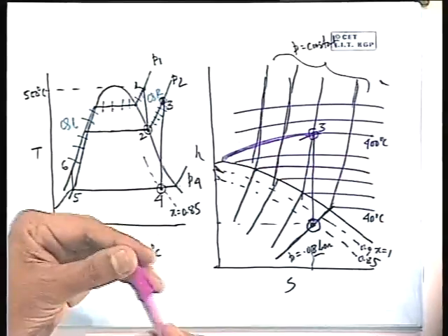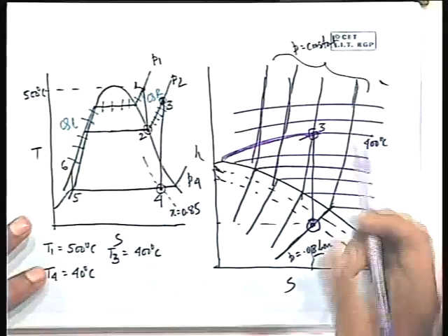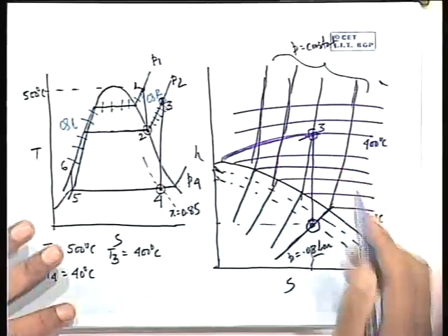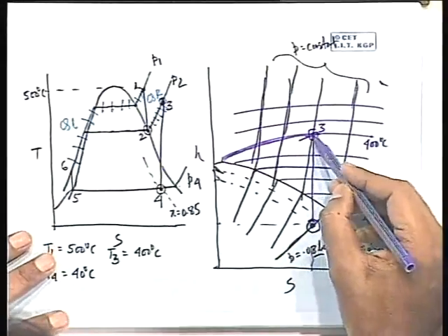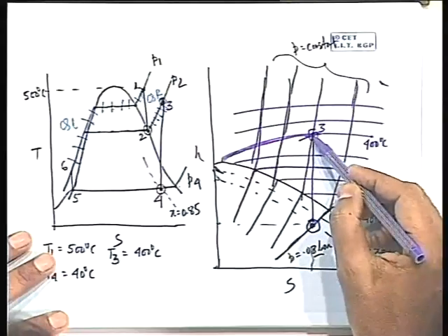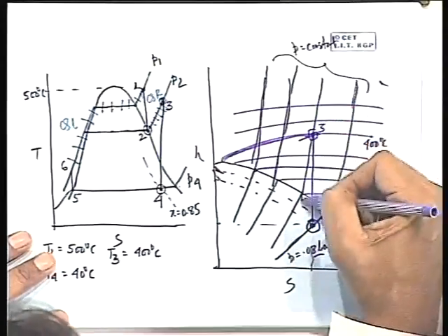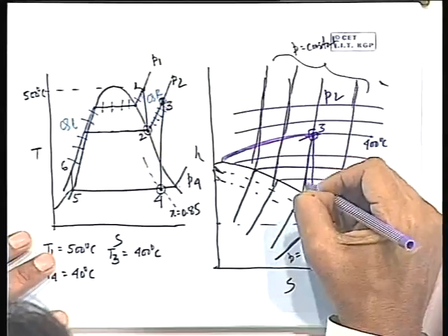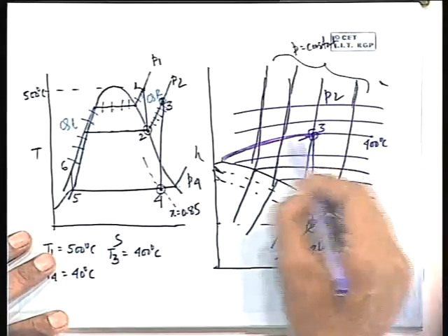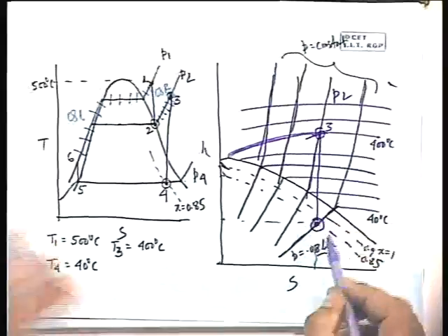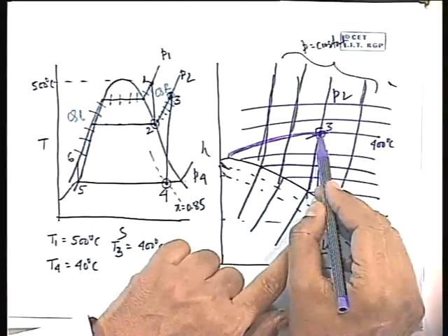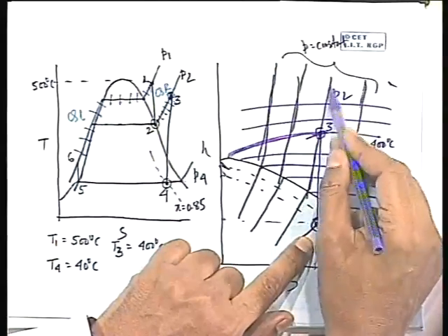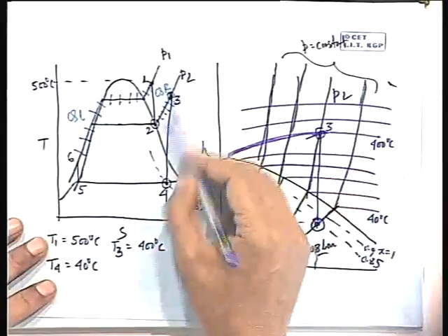Whatever is there we have to think, because the diagram is not very proportionate in geometry, however it doesn't matter. So I know this point, and this is the reheat pressure, that means this pressure is P2. Now I cool it at constant pressure, that means I can read the point where it cuts an isobar line. This point cuts this 400 degrees, so this point is P. Through this point there is an isobar passing, so this isobar is P2.